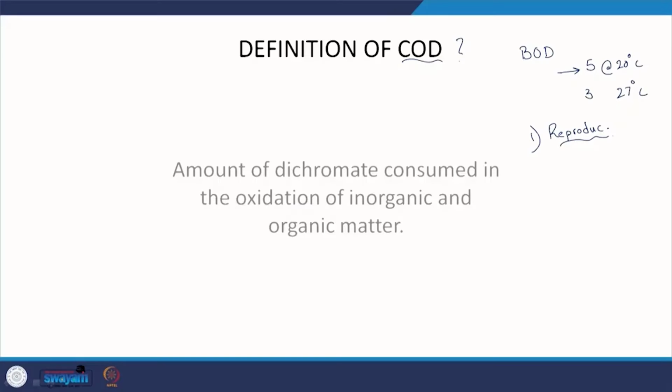Because of the kind of seed bacteria that you are using, as we mentioned with respect to the BOD test, it is all about the microorganisms consuming oxygen while degrading the biodegradable organic content. So, the kind of microbes and the kind of waste play a role, and if it is not domestic sewage or wastewater from our kitchens and toilets and such, reproducibility will certainly be an issue, right. And obviously, as I mentioned, 5 days, so it is relatively slow, right. Thus, people would typically want to look at relatively faster methods.